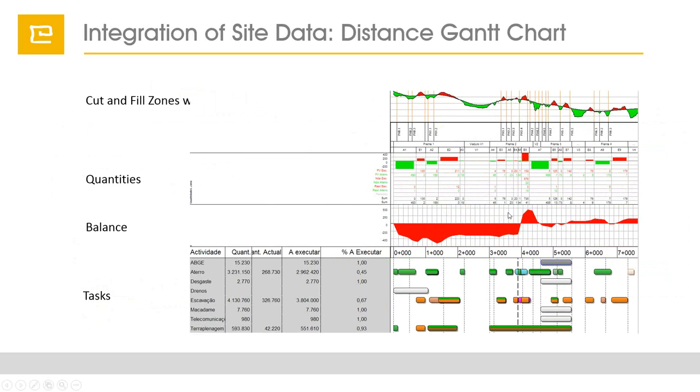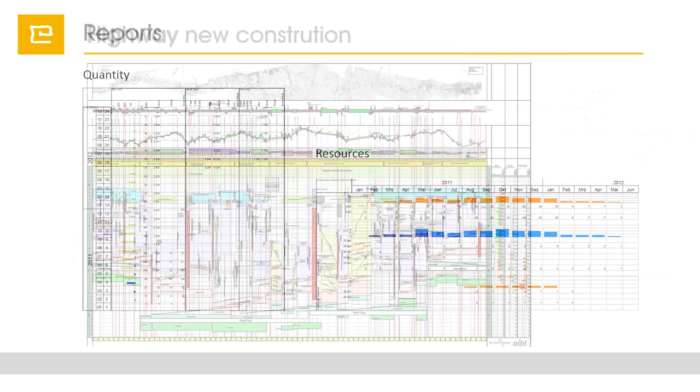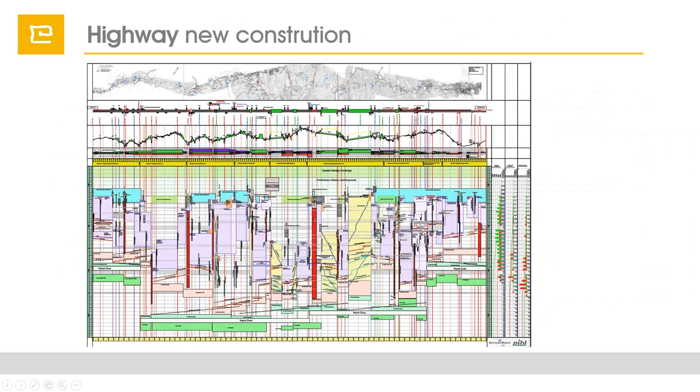Of course, TILOS can show the histograms along the time axis and the distance axis, horizontally or vertically, and compile this into a real schedule. It looks then like this. This is a 45-kilometer long road project that was done in Norway, where the bidder used this in the early project stage to calculate all the needed quantities and labor works in order to build his estimate.